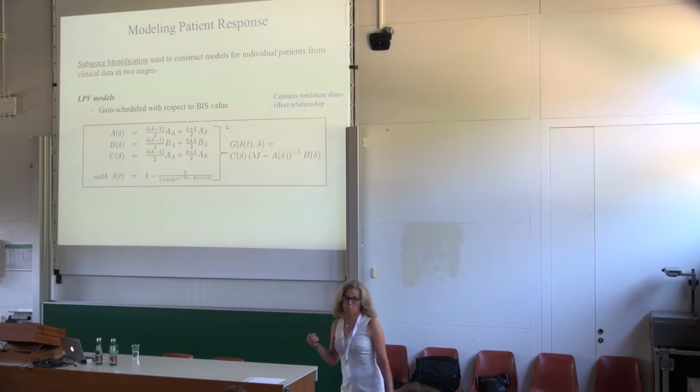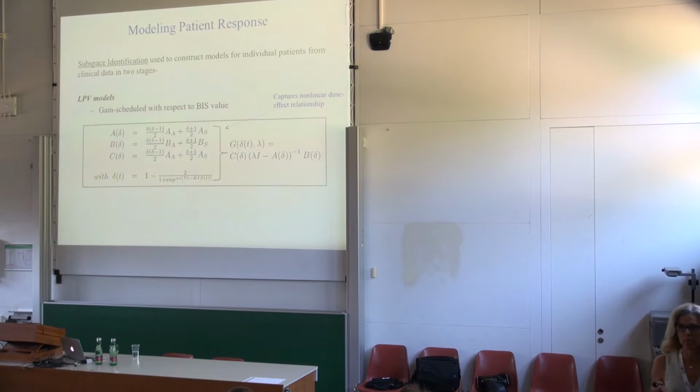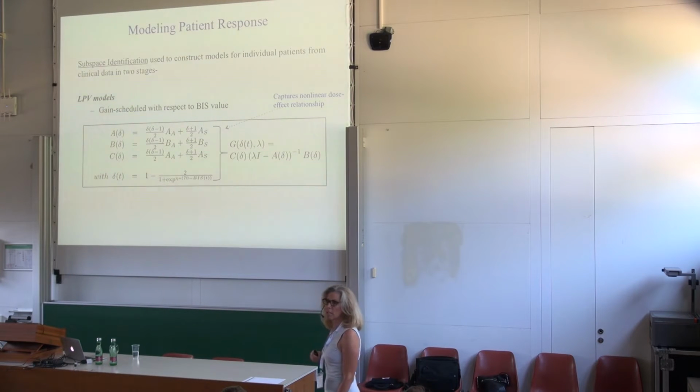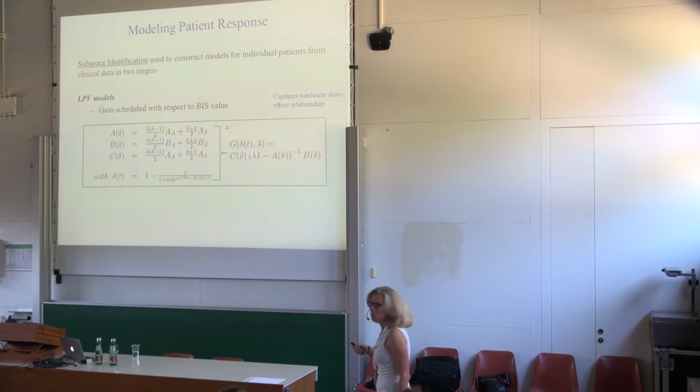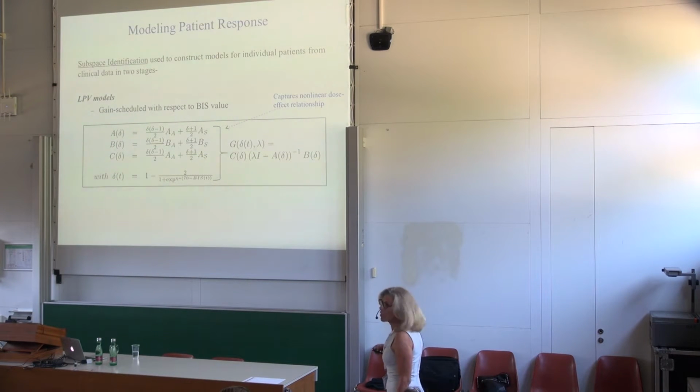Then from the piecewise linear models, because we wanted to do LPV control design, it gave us some robustness guarantees. There weren't very good methods for doing switching feedback design with guarantees at the time, so this was done between, say, 2000 and 2006 in my group. So we converted our piecewise linear models to linear parameter varying models.